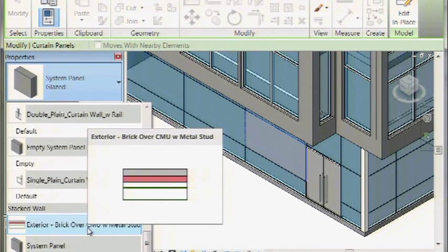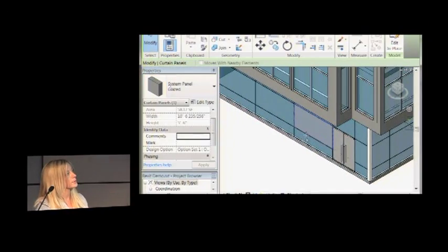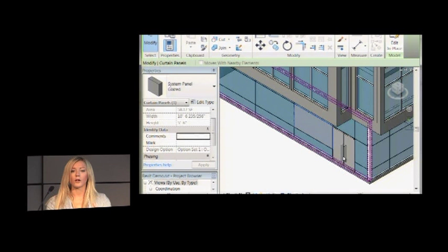So say we had a very tall building that's 10 stories high, and at the edge of the building, maybe where the floor intersected, I wanted a 5-foot area that was going to be a solid wall. What I would do would be grid my curtain wall, like perhaps this bottom area would be the solid, grid my curtain wall and make it solid, rather than stack walls on top of each other. 100% of the time, that's going to make it translate much better. Because anytime you can use one wall instead of stacked walls, it's much cleaner.